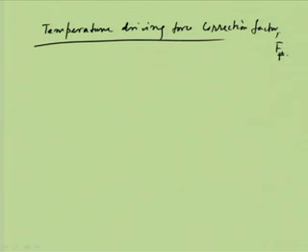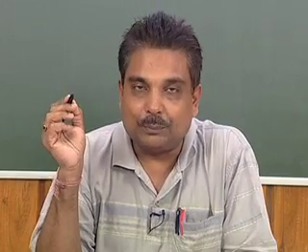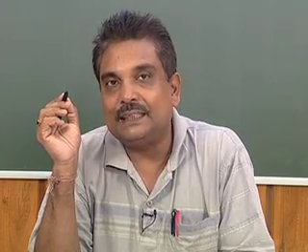Now, what happens in the case of a shell and tube heat exchanger, as we have seen, particularly for a multipass heat exchanger, is that the flow can be a mixture of parallel flow and counter flow. None of the flow is perfectly parallel, and none of the flow is perfectly counter. Therefore, the actual LMTD, the actual driving force, is different from what we can calculate. So, the actual driving force is calculated from the log mean temperature difference, LMTD, multiplied by a correction factor.